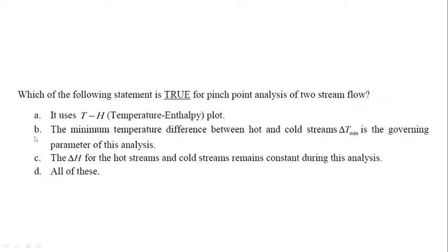Statement 1 is true, that is, pinch point analysis uses temperature enthalpy plot. Statement 2 is also true because delta T min, that is the minimum temperature difference between hot and cold stream, is the governing parameter for the analysis. And statement 3, that is, the enthalpy of hot stream and cold stream are constant during the analysis. So all the options are true. So the correct answer is option D.